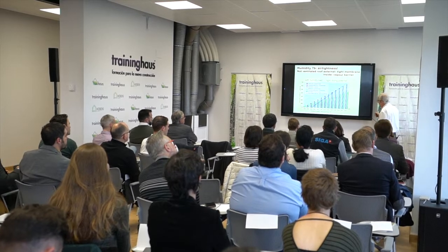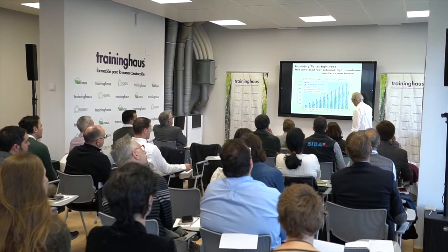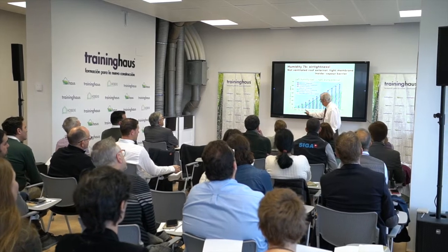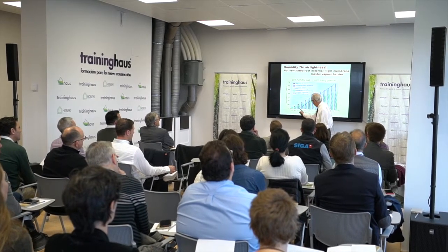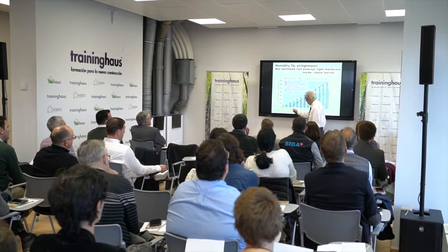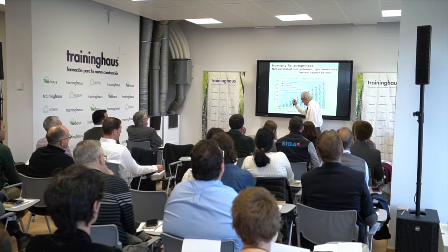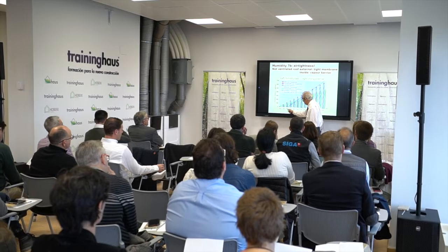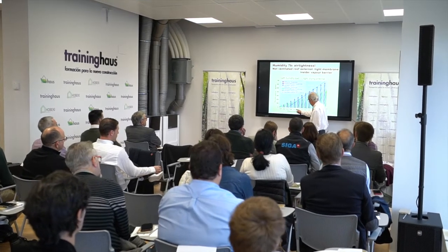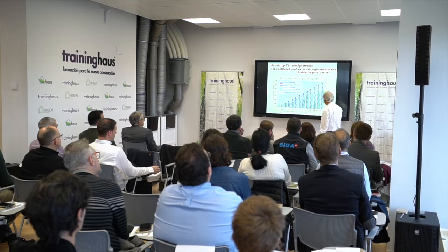And that means that if the air tightness gets worse and worse, this is what I show here. This is a result of 0.4 air changes per hour. I recalculated it to have an easier measure to tell, because you might all know about pressurization results. And we have higher untightness levels, to 2.4.